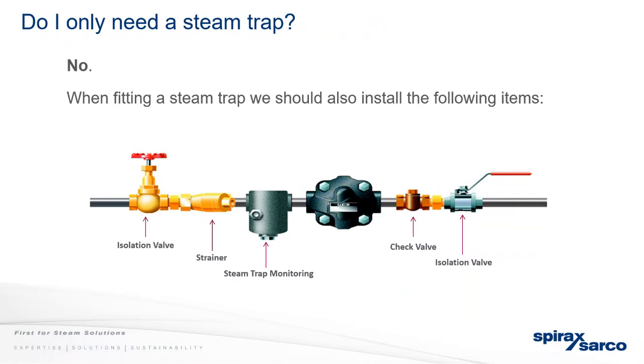It's very seldom, just a comment from my side, that we actually see that steam trap monitoring. We are looking at various different options in terms of wireless steam trap monitoring, continuous monitoring. Continuous monitoring is obviously becoming more and more important, especially when people start talking about their sustainability goals, sustainability targets, net zero, etc. Steam traps can actually have quite a big impact for plants with that.